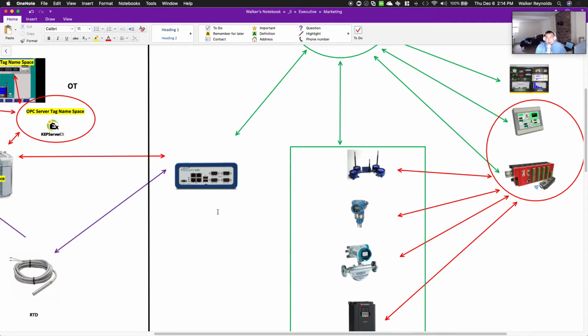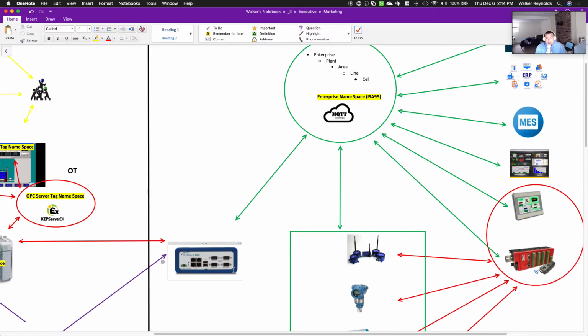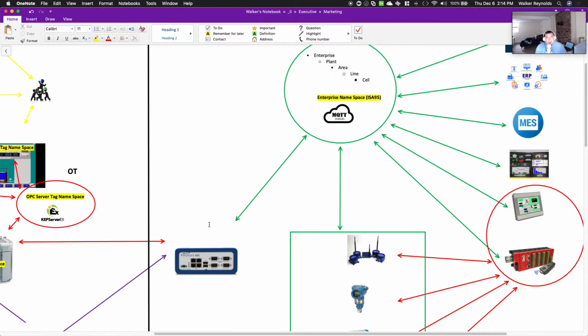I personally prefer the Maple Systems CMT SVR. So I generally put the Maple Systems CMT SVR in here. It's about $300. This is more expensive than the ReadyGates. But the ReadyGates talk more serial protocols and that kind of stuff. But Maple Systems, in my opinion, makes the best gateway. What I would say is the second best option out there is to use Ignition Edge.